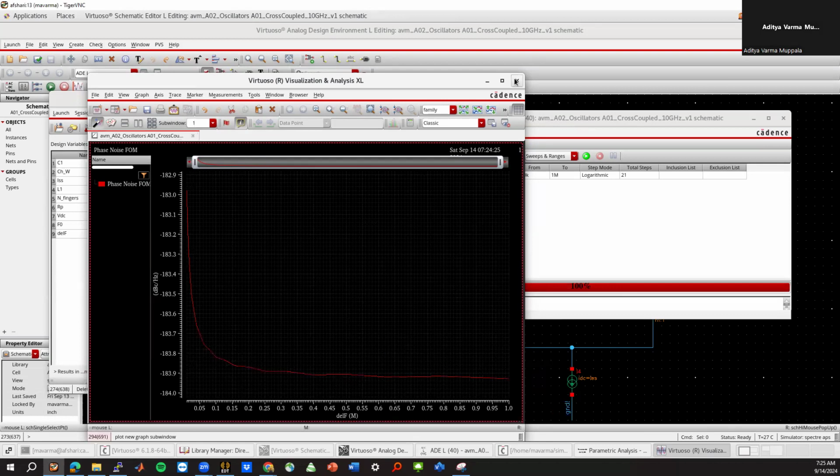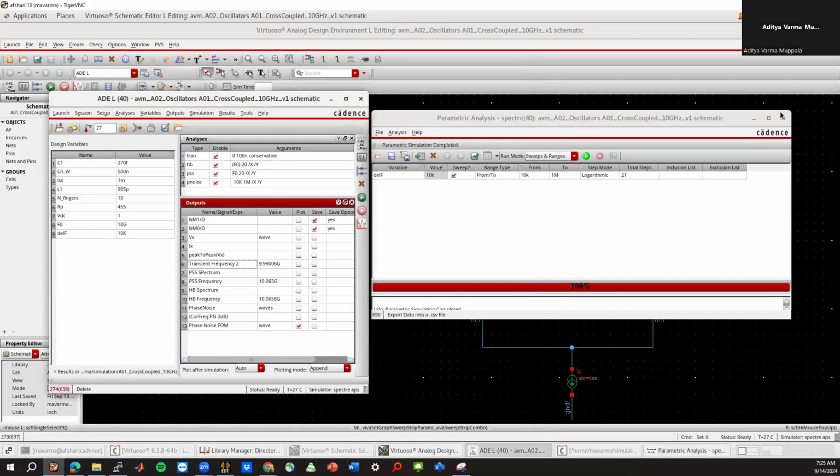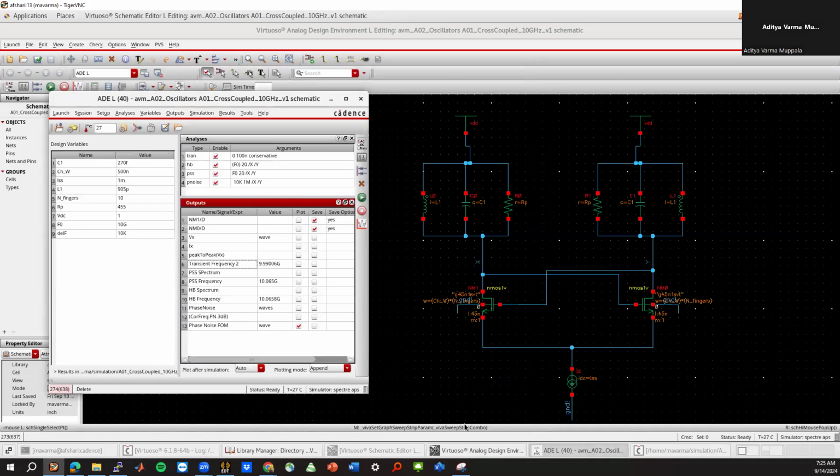So that pretty much concludes what I wanted to show you today in this video. We looked at how to set up this simulation that we started with. We did the analytical calculation based on Behzad Razavi's design procedure, more or less the same as what he proposes. And we looked at different ways to simulate it using transient, HB, PSS, and P-noise. And we said, okay, PSS is probably the most accurate way to do this because it's a free running oscillator that has some periodic steady state. And then we looked at how to extract the frequency of oscillation, the power at each node, the differential voltage and current. And we saw that the swing looks pretty much correct. And finally, we looked at the phase noise and how to extract the phase noise figure of merit, right?